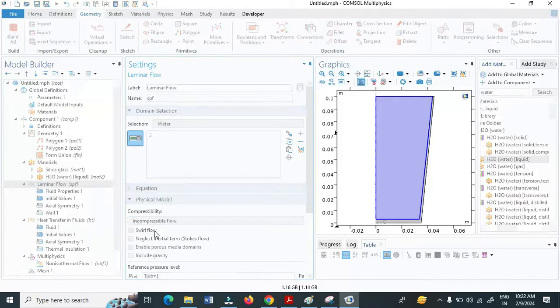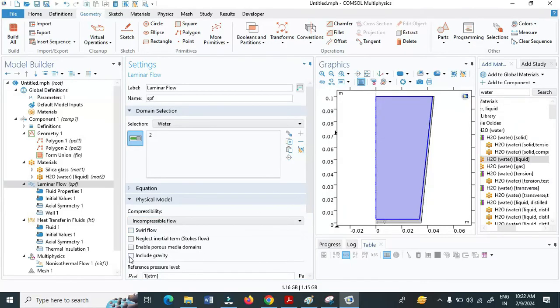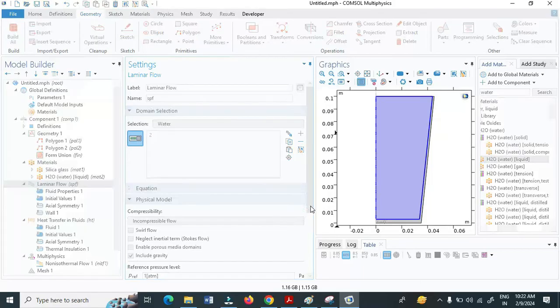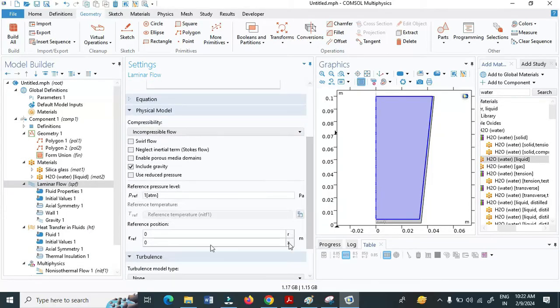So I'm going to give my radius as r top minus thickness of the wall, and this position will be my h g. I give the reference point. Now next thing is, click on physics and under points select pressure point constraint. I'm going to fix this point as a pressure constraint and let me select point number 6.